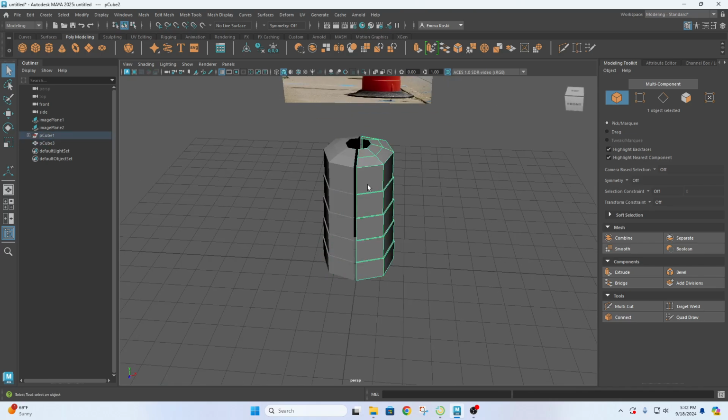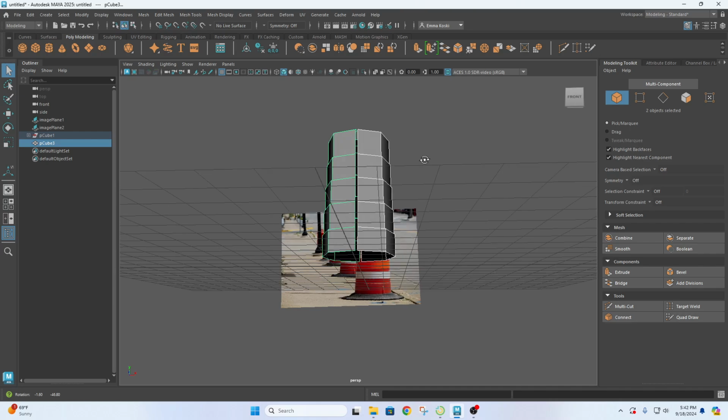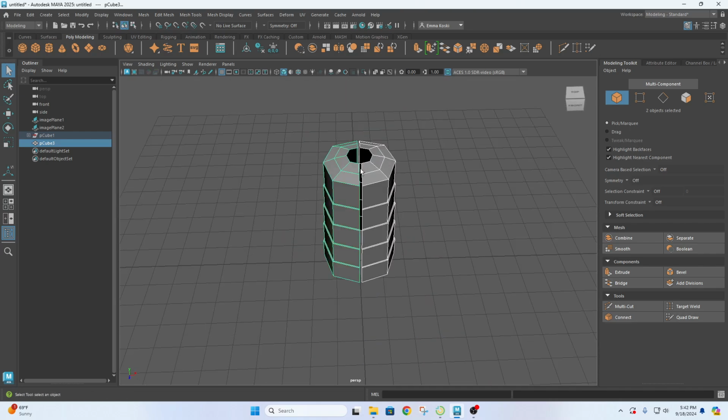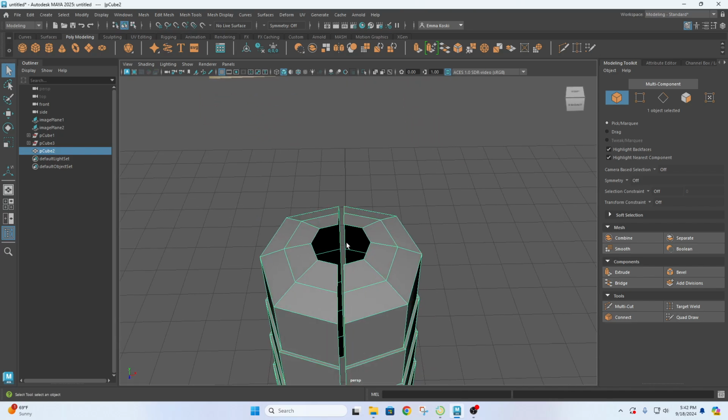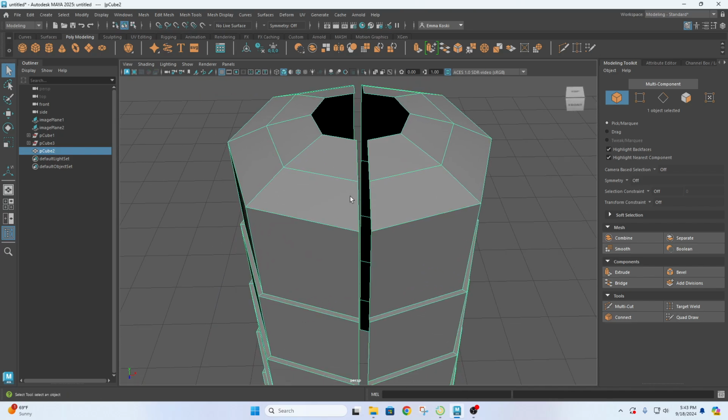Okay, that's good. I want to combine these together so that I can weld them back together. So I'm going to select both, click on one, click on the other, going up to Mesh, hit Combine. Okay, so now it's one object. Now I need to bridge this gap, right? For you, if there wasn't a gap, then you could still have the issue of overlapping geometry.